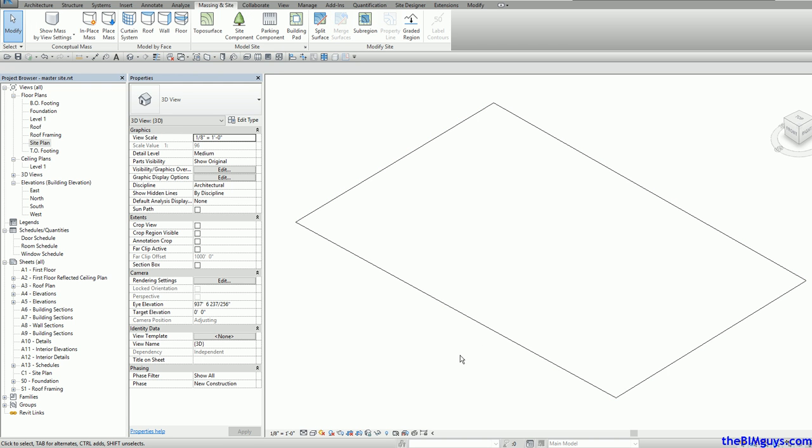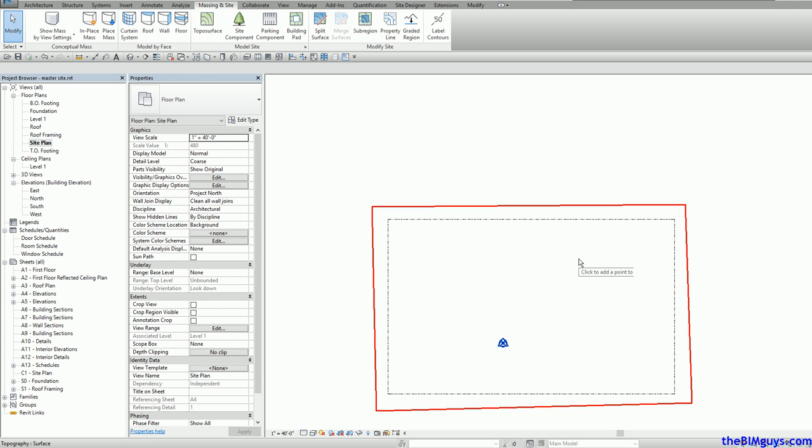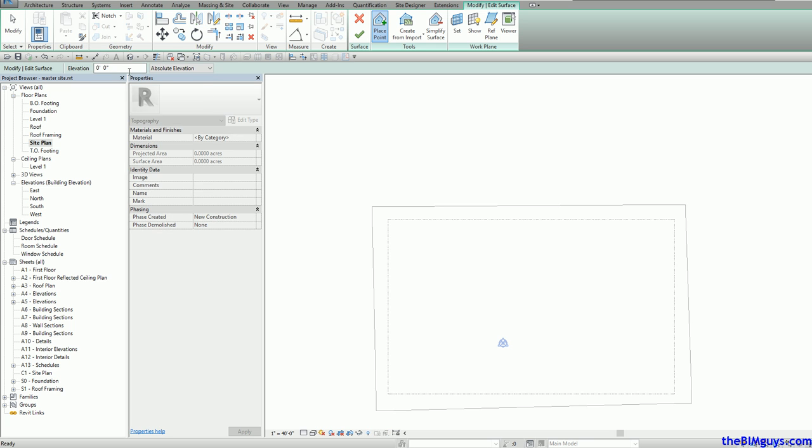Because of the site. Now, once you've gotten the site, you may decide that, I'm going to go back to my site plan, that you want to berm up some area. Maybe you've got something back here you don't want to look at, you want to put a berm back here. Maybe bring the land up, maybe you're building a pond, right? You want to bring up a berm in the back. You're going to click on this thing and hit topo surface again, and you can then add and subtract by putting higher numbers and lower numbers in here.